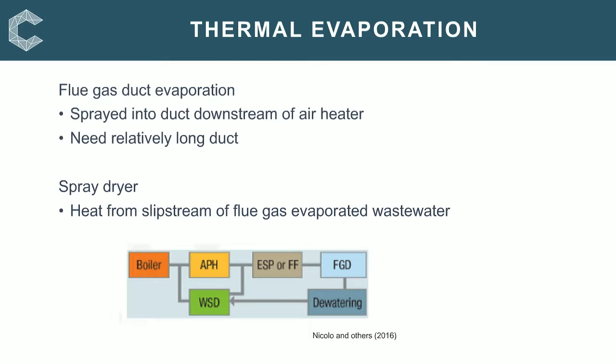Of course, the amount of water that can be handled is limited by the amount of flue gas available and the need to maintain the minimum temperature required for the ESP or fabric filter operation. It also needs a relatively long flue gas stack to evaporate all of the wastewater. In addition, the residues will contaminate the fly ash, which could make the fly ash unsaleable.